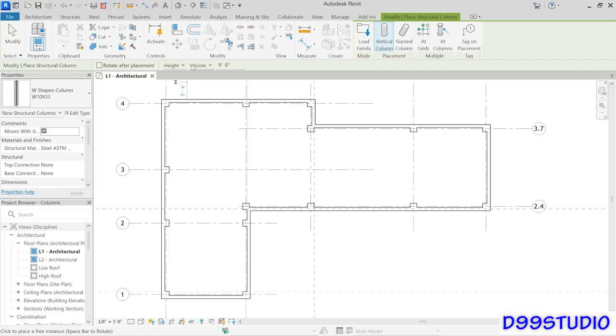And then you can even further establish the height either numerically right here, or you can use this drop down here and associate the height with one of your levels. So I'm going to choose level 2 in this case so that my columns will all start at level 1 and go up to level 2. The benefit of that is later, if we move the height of level 2, it will automatically adjust the height of all those associated columns.